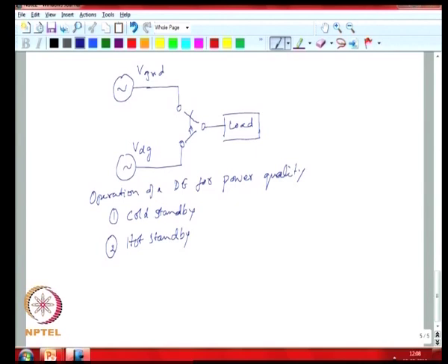output voltage, or many UPSs can actually start up in a much shorter duration depending on how quickly you can start up your inverter. So that would correspond to a hot standby basis, which means that essentially you have voltage available, and in this particular case the speed with which you are able to transfer over is then entirely limited by the speed of the switch.